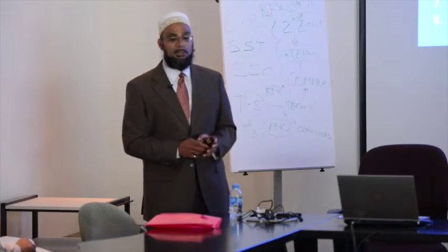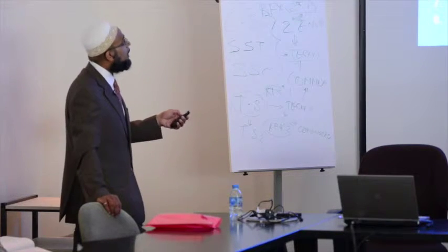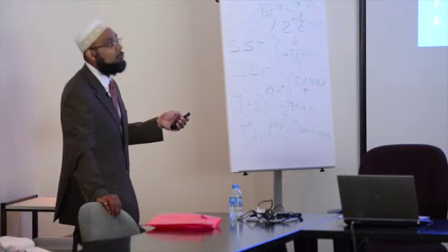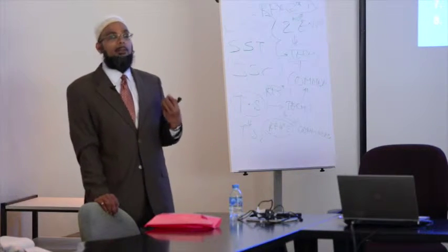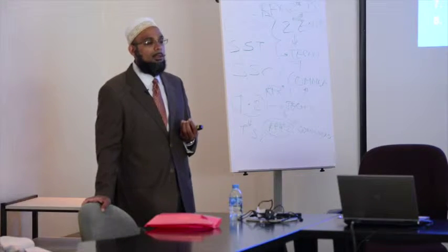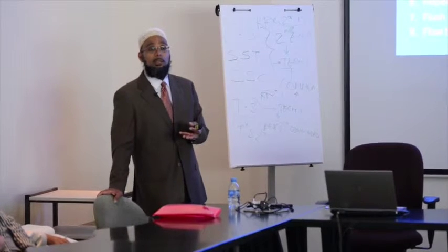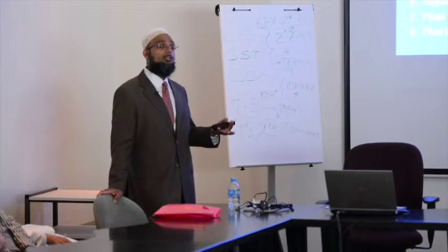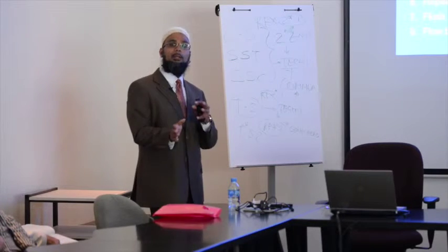Okay, now here are some of the treatment design elements, some steps that we go through. The first one is the treatment flow path selection. What I mean by this is we have to decide if we are going to inject the treatment through coil tubing or through the production tubing. So we're going to bullhead or we're going to use coil tubing. Whichever flow path you select, we need to pickle it.